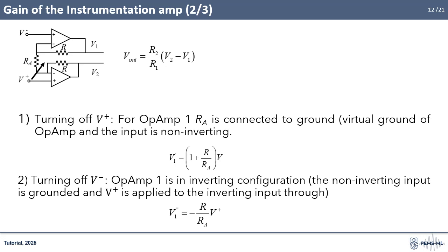It can be stated that the differential output is proportional to the given formula. This formula highlights the practical advantage of the instrumentation amplifier. Engineers can adjust RA to set the gain precisely without impacting the input impedance or the matching of the other resistors.